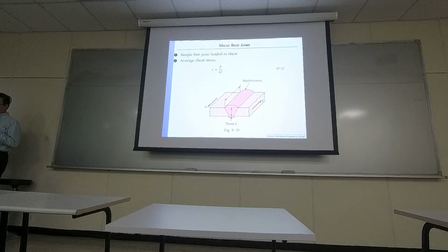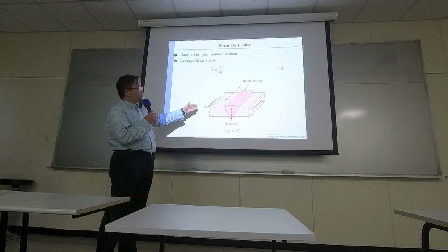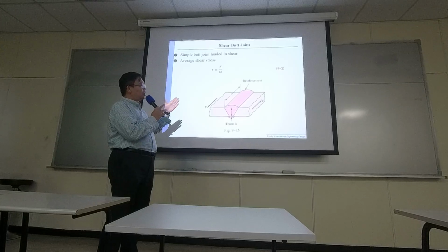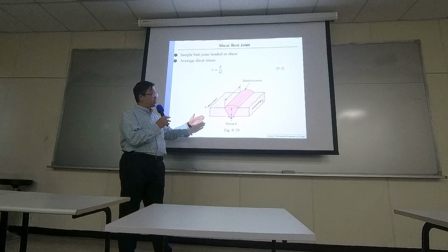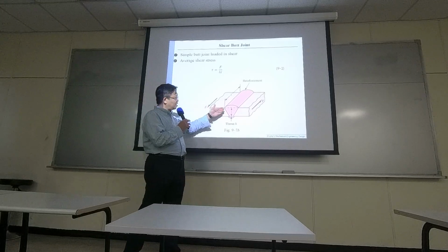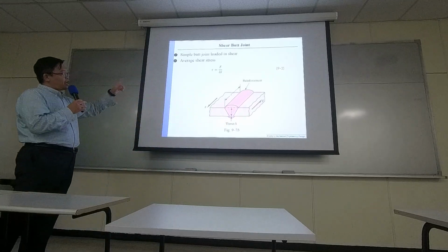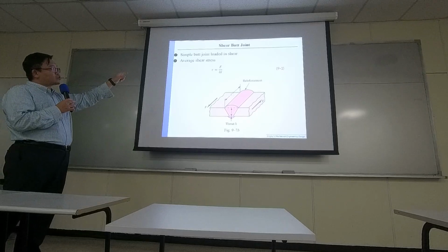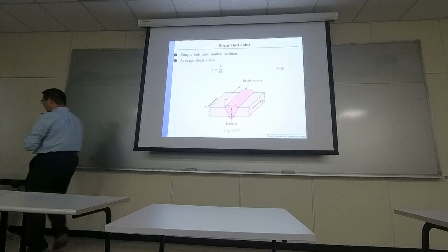For shearing, similarly, if you have shearing forces that is lying along the geometry, the cross-section, then the effective area, the stress area, is still H times L. So for this particular case, the shearing stress equals F over H times L.